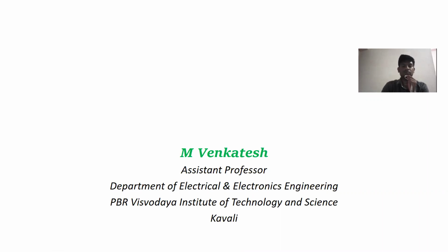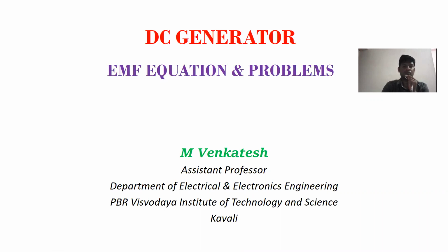In this video, I explain the derivation of the EMF equation and problem solving on the EMF equation. So, what is EMF? EMF is nothing but a force which drives the electrical current in an electrical circuit. In the DC generator, they induce the dynamically induced EMF, that means it's a rotationally induced EMF. So that is the EMF we get from the generator.